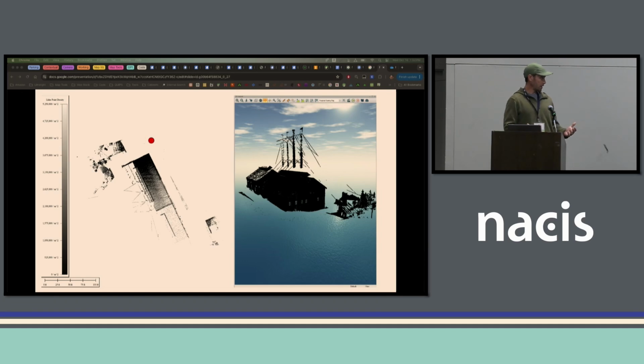I don't have a lot of pictures from this process because I wasn't thinking about doing a presentation on this, but here's a single one of these files. I put a red dot where the base station was. One of the core problems with working with this data was 98% of the data was within a 2 to 5 meter radius around the total station. So I have a sub-centimeter accurate model of the surveyor's Gatorade bottle right next to the total station, but not the back side of the building that I'm actually looking for. So after I erased all the Gatorade bottles and rocks away from this station, I ended up reducing the data footprint by 98%, which somebody could have emailed me.